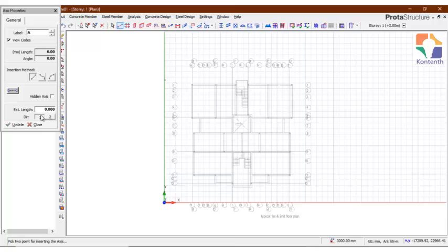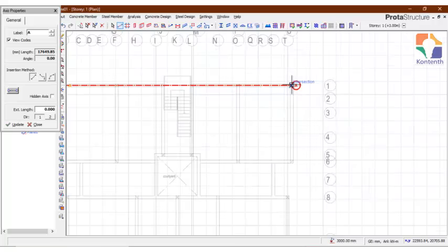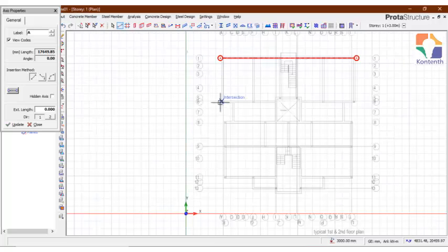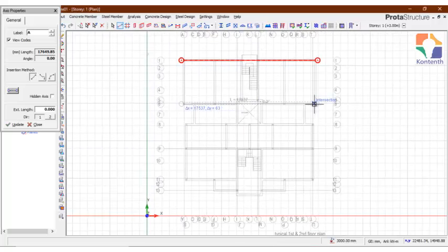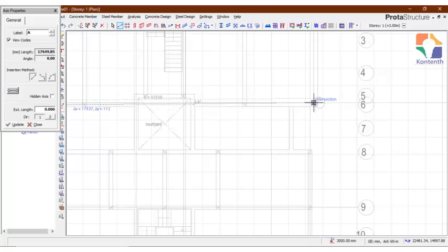So this is to tell you that you must understand what you are doing exactly in order to create what you actually expected, or else you would be creating the wrong thing. So let's select the direction 1 axis and create an axis just by snapping to a particular point. So we have that created. I want to put another axis here also. Put another axis here too.